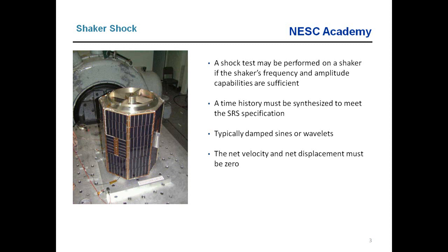Now, a shock test may be performed on a shaker table if the shaker's frequency and amplitude capabilities are sufficient. And anytime we can do a shock test on a shaker table, that's a good day, because this type of shock testing tends to be more repeatable than other types of methods. But there are some limitations. It's only good for either benign to moderate shocks, and certainly not for pyrotechnic shock simulation.